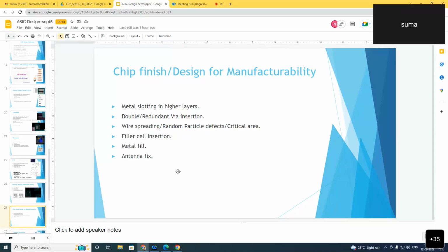Timing awareness is also needed when we do the engineering change order, ECO, which arrives late in the design cycle. This requires the designer to change the layout in case the fill has affected any area, so during this ECO we need to fix that. Thus, the fill methodology should allow us to easily remove and reinsert these fills without violating the timing of the nearby nets, which is a major concern.